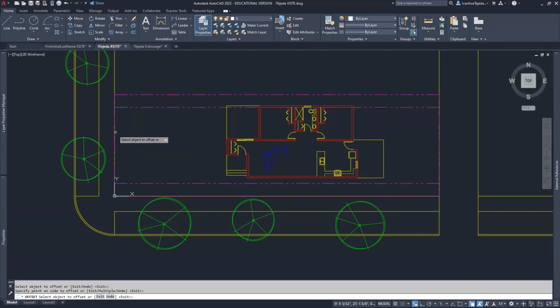I'll go ahead and pick this line here. I do want to pick the property line in this case, so I click on that line. But instead of 5 feet, I want to bring that in 20 feet and enter. And then I'll pick this property line back here. And I'll select that line. And I'd like to bring it in this direction, 20 feet. And then enter. As long as I'm within the parameters there, I'll be okay.